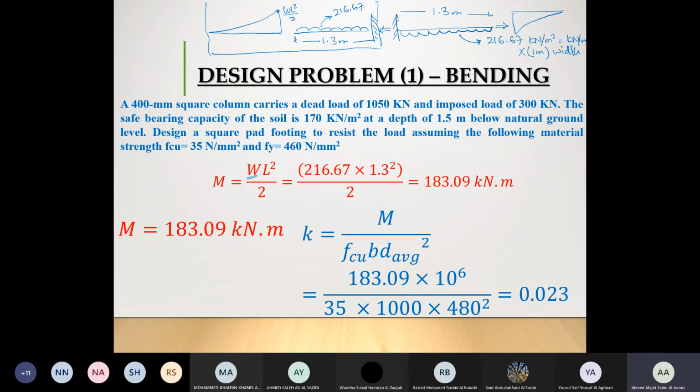Now, if we have different lengths, then you should be taking into account, if you want an accurate result, dx separately and dy separately. The average should be used mainly when it comes to shear reinforcement or shear check, which will be seen later. Okay. Now, in this particular context, or for the student level, even if you have L1 and L2, you can take average. Okay, you can take the D average, which is for the student level now.